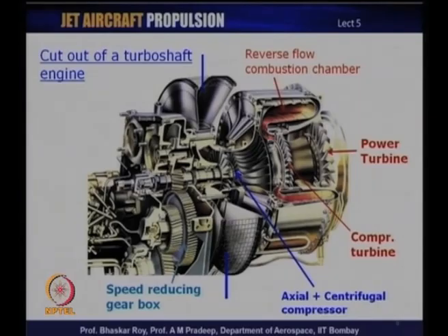However, the rotor cannot possibly run at anywhere near that speed. So, you have a huge reduction that needs to be done, and you have almost something like a gear train through which the reduction needs to be done in an efficient manner, and this reduction could be of the order of 1:100 or something, and as a result you can see a huge big gearbox.